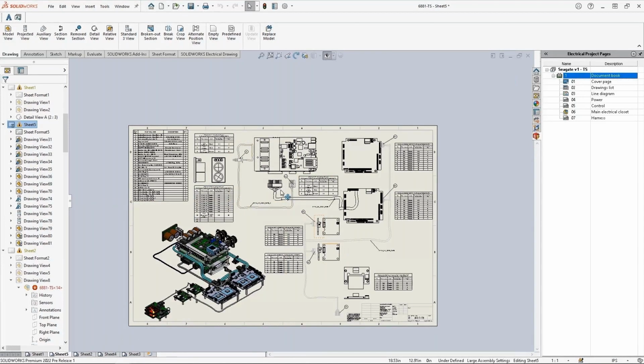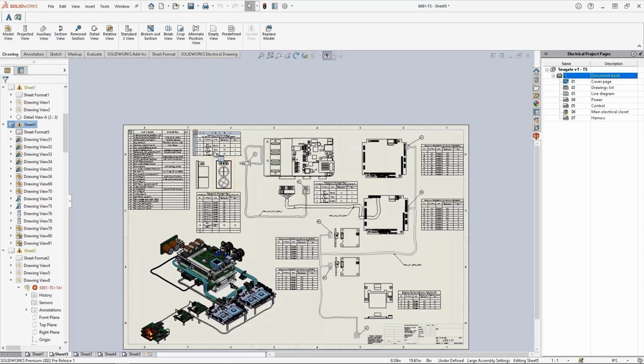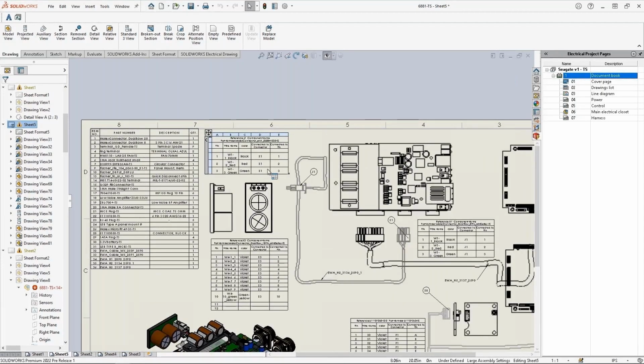Everything that you're looking at as far as a table, a callout, a balloon, is driven by the application. The metadata contained within them, driven by the system, comes from schematic information, right? So I'm defining these connectors. I've defined all this wire to and from information. But when it comes here, it's like putting a puzzle together, right? I have the metadata. I'm just selecting the views, where I want to place a view, etc.